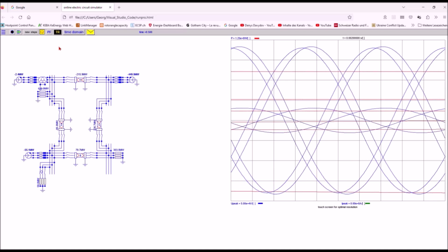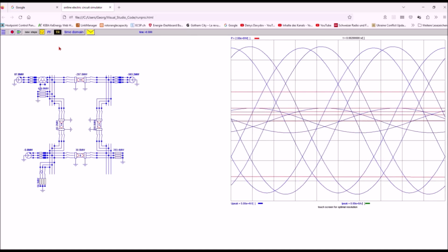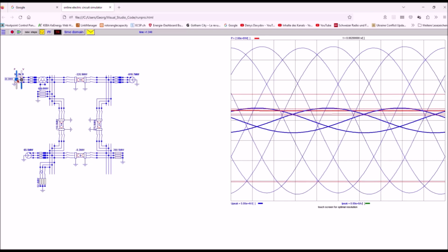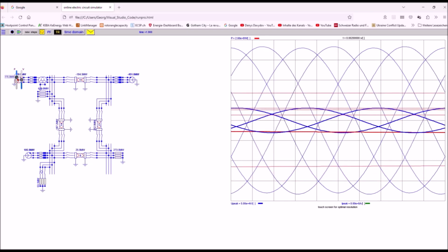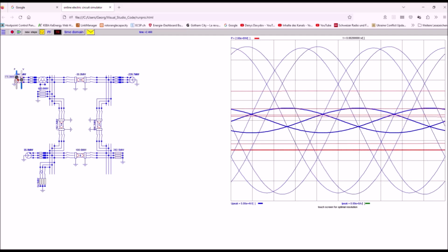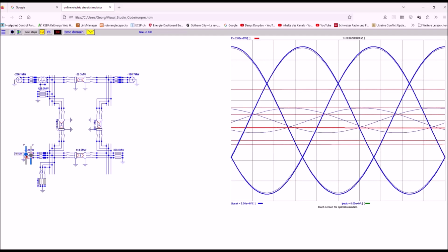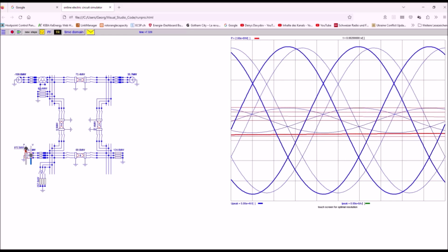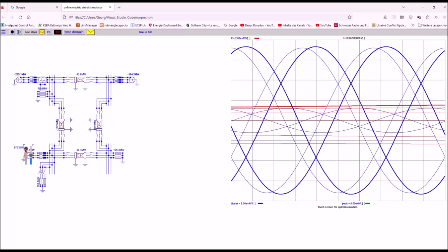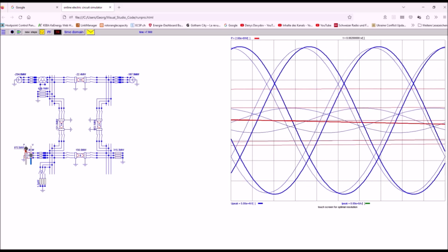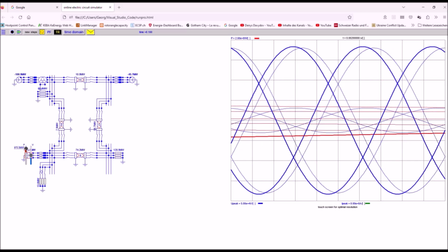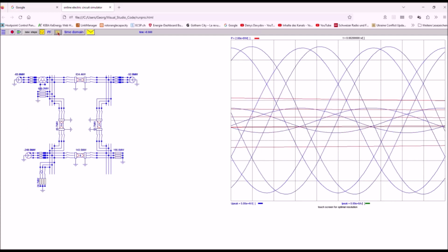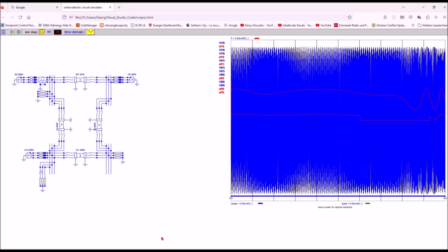As long as the simulation runs, it is recording in the background and you can interact with the simulator as usual. Here we increase the phasor angle of the machine beyond the limit of 90 degrees and therefore we have a rotor runaway, and later we will see how this looks like in the transient recorder simulation. Let's now click the recorder button again so we get the transient recorder traces.